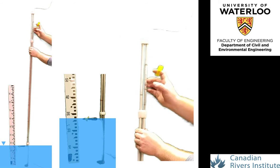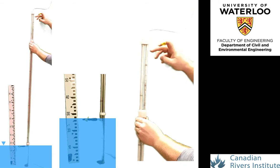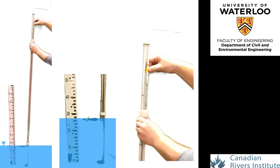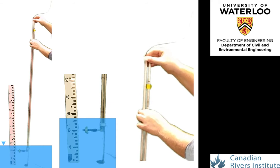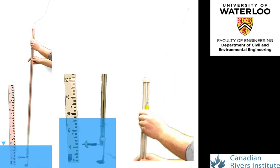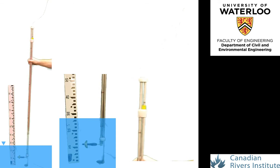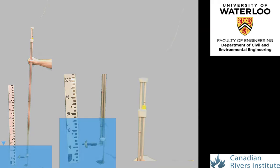The number of hatches are then counted down on the sliding rod: 5, 10, 15, 20, 25, and proportionally a bit more to get to 27. The bottom of the yellow tape here denotes the proportional position on the sliding rod. The sliding rod is now adjusted such that the base of the yellow tape coincides with the top set reference position. It is now noted on the staff gauge that the depth from the base of the rod to the center line of the flow meter axis corresponds with approximately 11 centimeters, or approximately 40% of the original 27 centimeter flow depth, 10.8 centimeters to be exact.